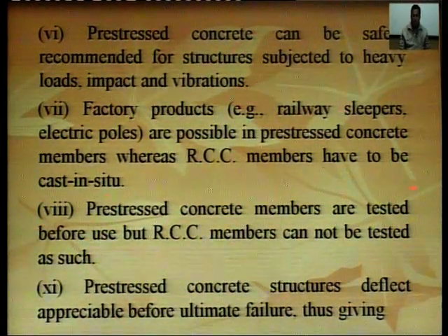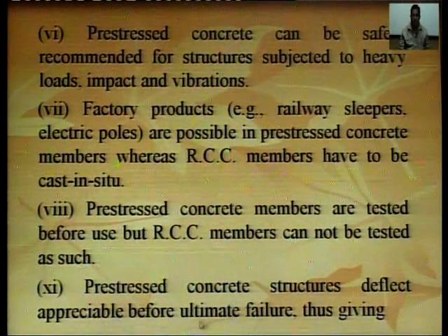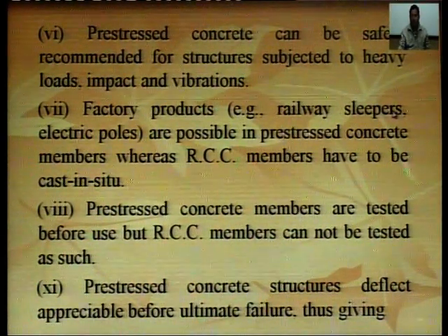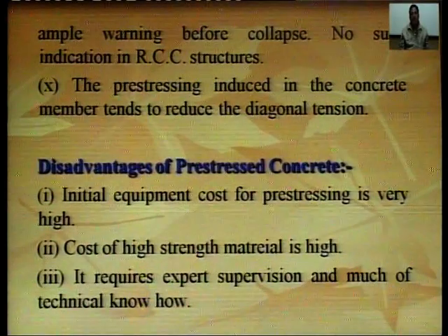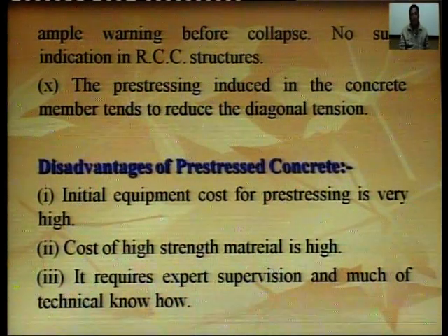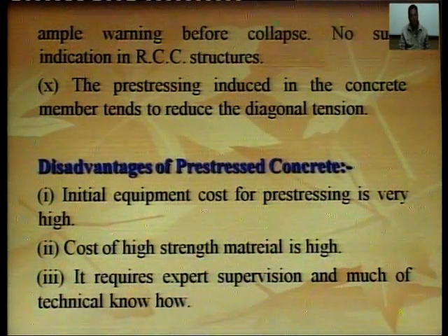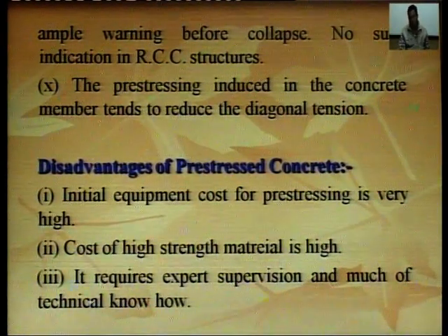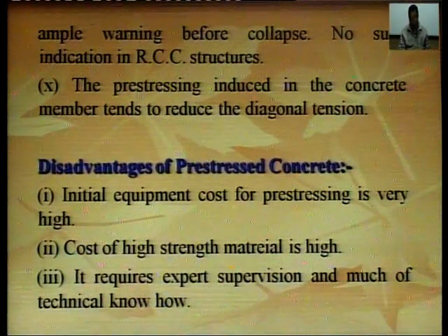Pre-stressed concrete structures deflect appreciably before ultimate failure, thus giving ample warning before collapse. No such indication in RCC structures. So, these sections give sufficient warning before the final collapse.